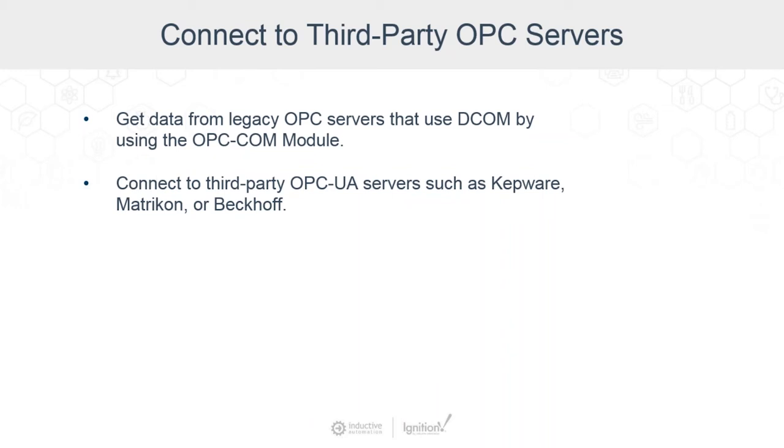So because of the standards that Ignition is built with, you can connect to any device. I think this is kind of the main point here. We built it on standards so you can connect to any device that's out there, either through Ignition's native OPC or a third-party OPC server. So we open the floodgates to making that data available.